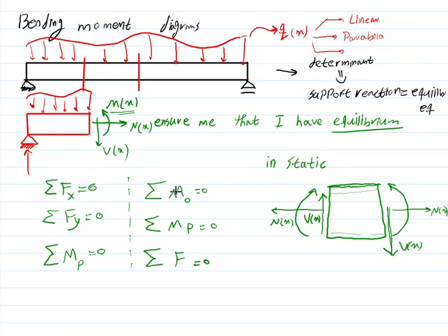So until here, we understand that there's nothing hard about it, but what makes it hard is the resultant of forces and how M(x) and V(x) change throughout the length of the beam. There are several ways to actually draw the bending moment diagram.